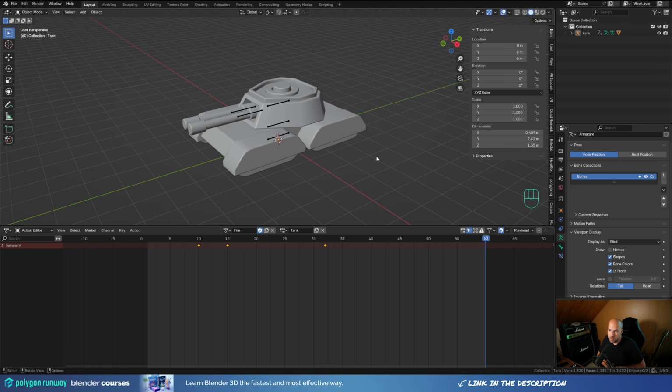So I will first do some quick texturing using procedural add-on Fluent Materializer. This is a paid add-on and I use it a lot, and I'm in no way affiliated with the add-on maker. I just use it a lot, and it will be much quicker to show you how to quickly create that kind of texture. And of course then you can decide whether you want to go for the add-on or you want to use some different means of creating your textures, whether it's procedural or from different texture maps, but the lesson here will be about baking the texture and exporting it along with the FBX to the game engine.